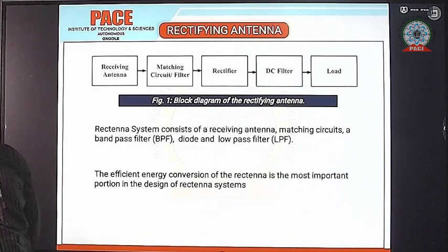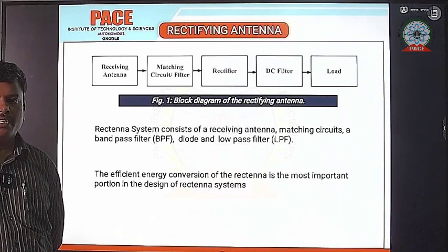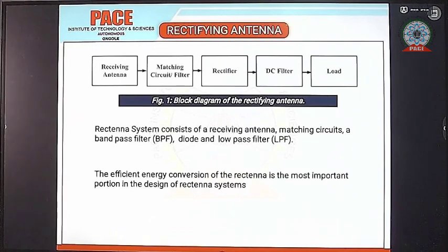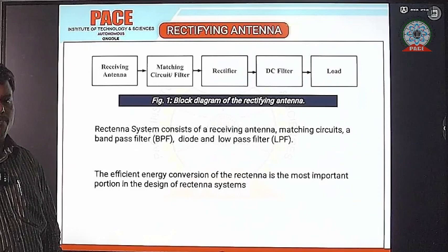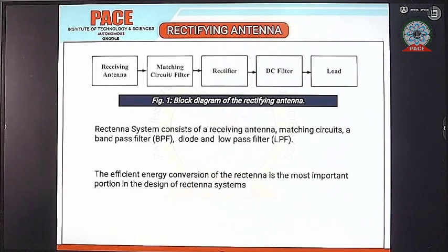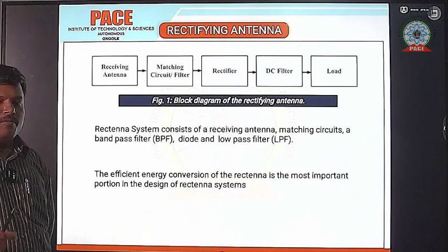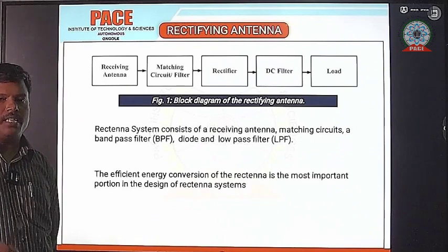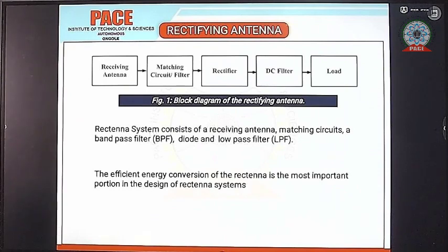If you use antenna arrays, the antenna receives even low RF signals. One drawback of the antenna array is that the beam width is very small, so the coverage area is also small. If you use circular polarized antennas, the antenna receives signals in both the XY plane and the YZ plane. That is the advantage. Next, wideband antennas: with wideband antennas, we can receive the RF signal over most frequencies. This is the process of receiving with the antenna.